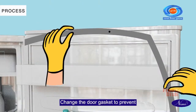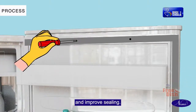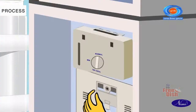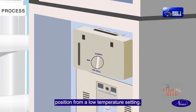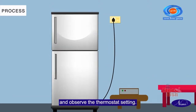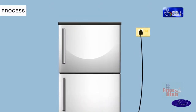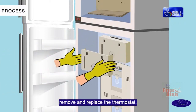Change the door gasket to prevent moisture leakage from the surroundings and improve sealing. Reset the thermostat to the normal cooler position from a low temperature setting. Allow the refrigerator to run and observe the thermostat setting. It should trip to a normal cool position. If the thermostat does not trip to a normal cool position, remove and replace the thermostat.